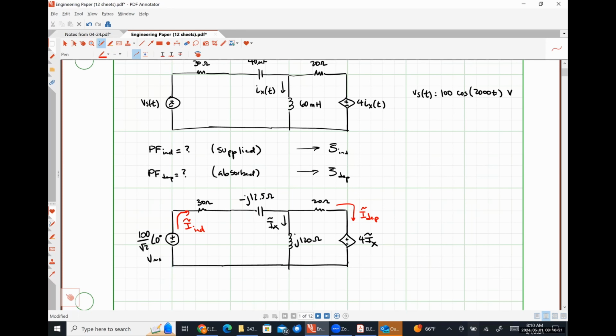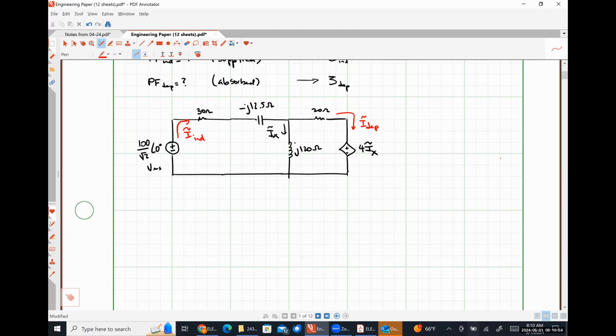All right. Well, since you guys are not volunteering anything else, I am going to talk about how I would solve this thing. So when I see a circuit like this, what I typically do is I'm going to call it a modified nodal analysis, but realistically, it's just applying Kirchhoff's current law and a little bit of algebra in order to sort things out here. So I use this method whenever I have only one unknown voltage in the system. So I'm going to redraw my circuit very slightly, okay?